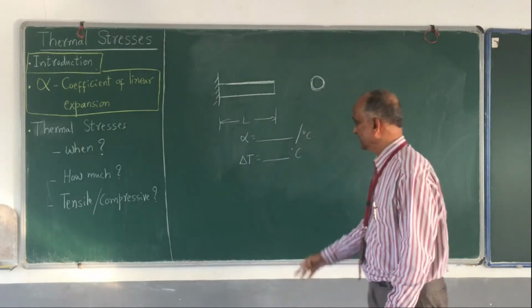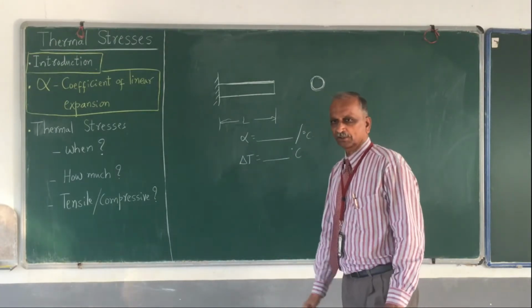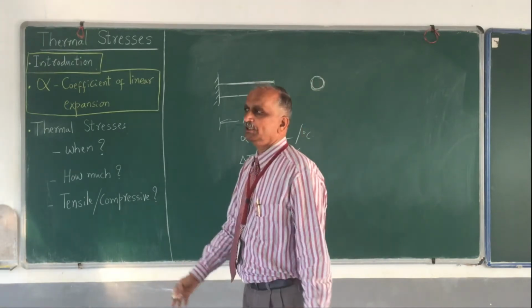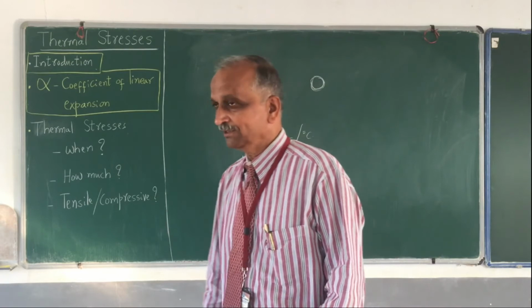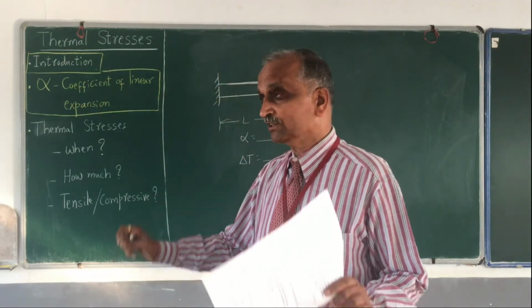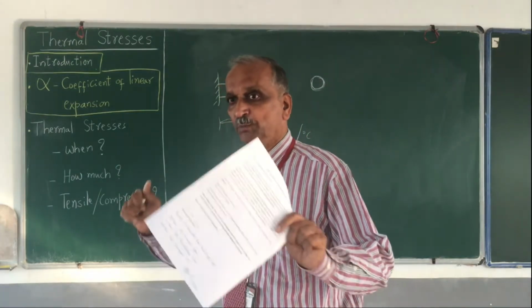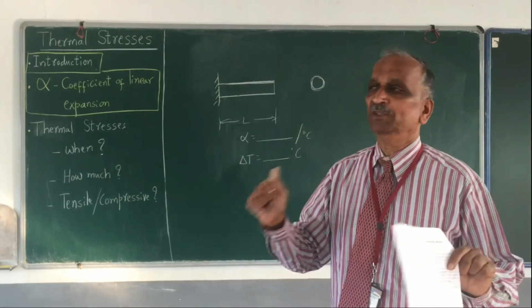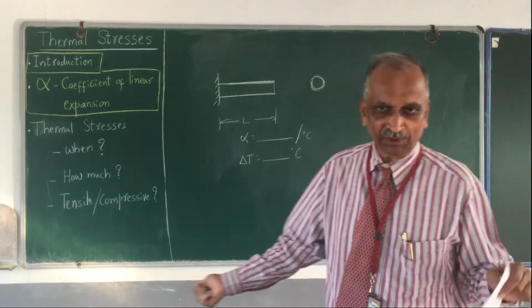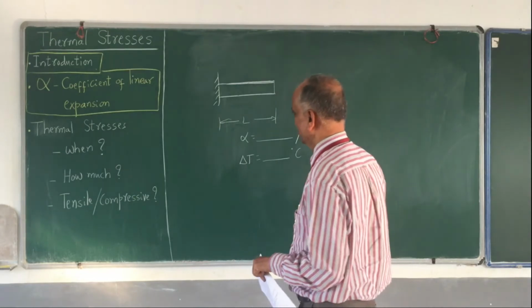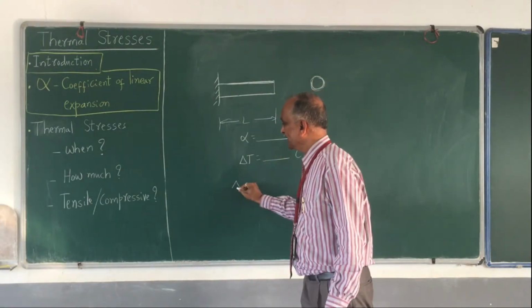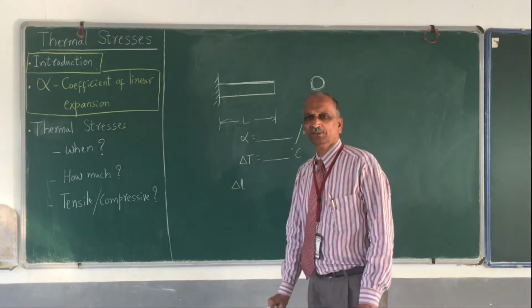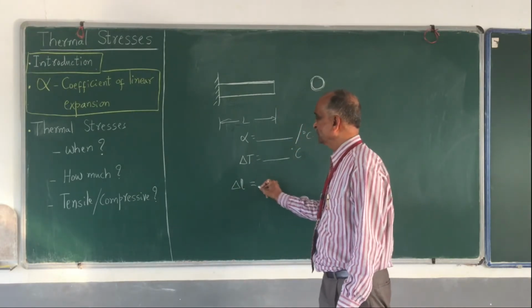It's per degree centigrade, this is so many degree centigrade. Okay, so I ask you, what is the stress in this? Again it's similar. Please remember, stress is going to come into picture only if it is subjected to any force. If you don't have any force, then there is no question of stress. So now immediately what I can calculate, what is the free expansion of this member? How much is that?